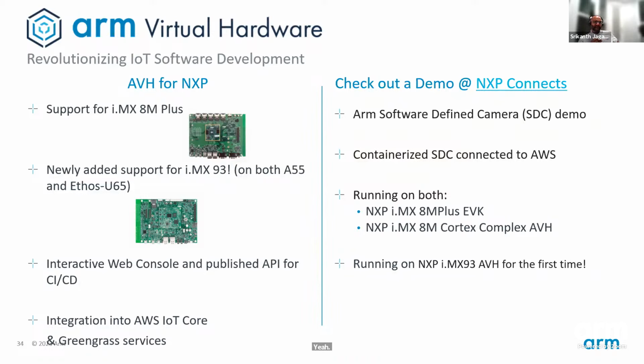Amazing, thank you. And then the last two questions: are there the M33 pins available hardware-wise? I don't know what that means, but M33 is a processor that is sitting inside the SoC. There are interfaces, which means there are pins or pads interfaces connected directly to the M33 to do real-time applications. If that is the question, then yes, we do offer them externally, but the M33 by itself does not have any pins or anything. It's just a processing unit sitting inside. Thank you. No, thank you for clearing that up.